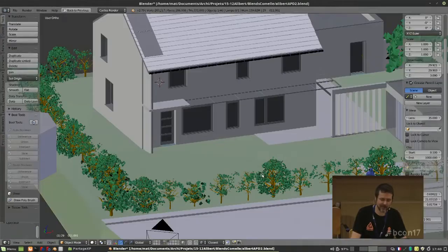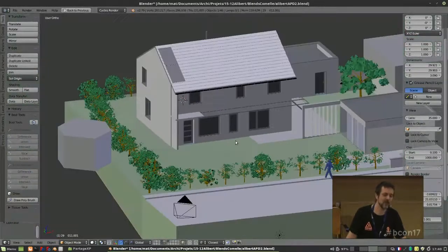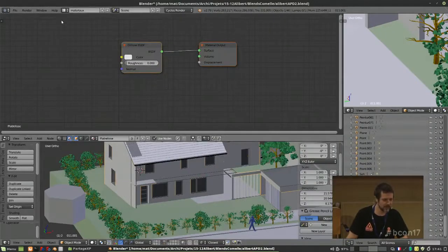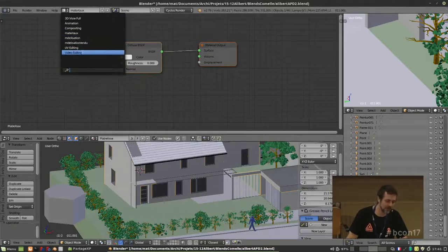If you don't have to go back and forth from the architectural software to Blender, it's very okay, because you know what you design in the architectural software, and once you are done in this one, you export to Blender, and then you don't move things anymore. Because if you start to make two-way exchanges, it will not work and you will lose a lot of things. But then you just have, as I told you, the UV mapping.